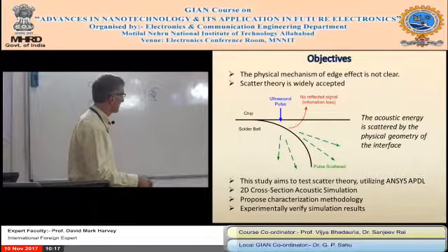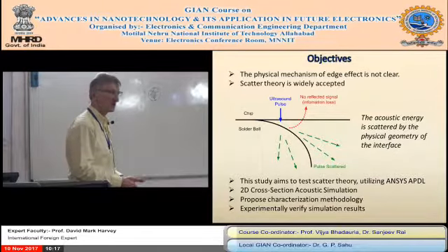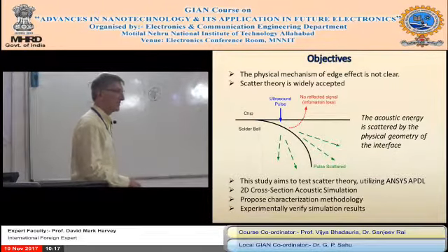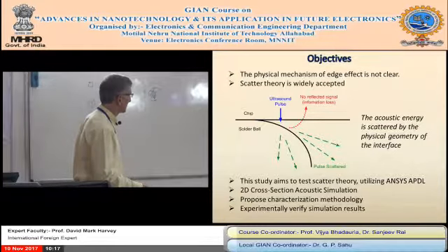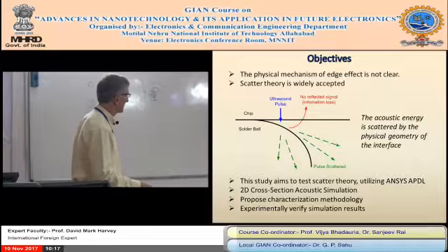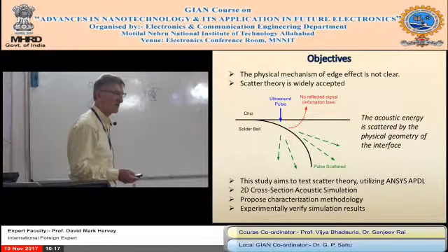It's in the water. And we'd expect some reflection from this point as well as where the chip meets the solder point. It's reflected very well at discontinuities due to the change in acoustic impedance. Higher the change, bigger the reflection. So it's scattered due to the edges, but we thought, well, there's something going on around here that we can't really understand experimentally. So we did the simulation first, and then we did the experiment to see if the simulation was correct, which is the best way to do it.